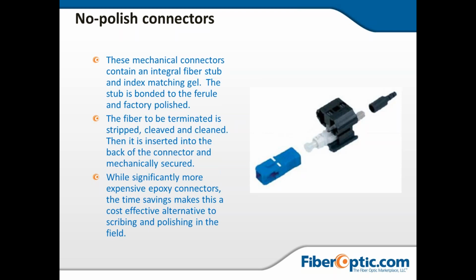You would simply use a mechanical connector just because it's more reliable, less chance for high loss, and even if there's a higher cost associated with it, the man hours for polishing and scribing add that much more to the project management side. So I don't feel there's really an option there, but there is an option, and that's something that's nice. That's just my opinion. So instead of scribing and polishing in the field, this is a nice alternative and can allow you to get the job done.